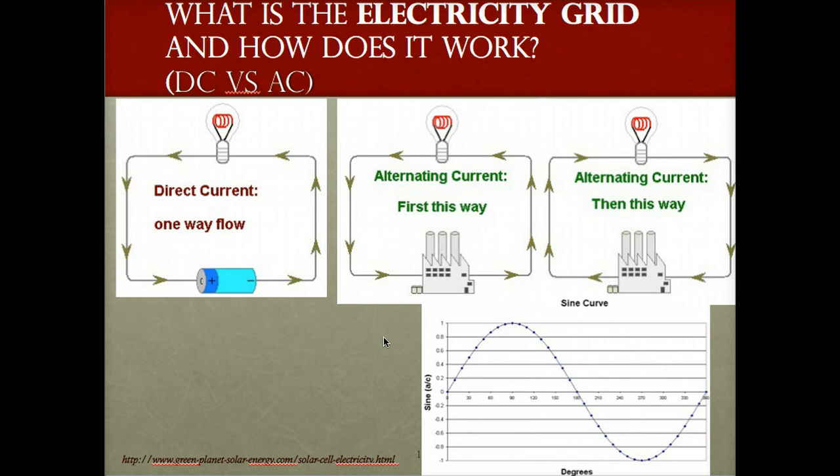One, you will be learning about the three main sections of the U.S. grid: East, West, and Texas. These sections are seen as completely different parts of the overall grid because they run on different frequencies. Although they all run on alternating current, their sine waves don't line up with each other. So if a generator in Texas wants to send electricity to Arizona, for example, that electricity has to go through a special and very expensive transformation process to be converted from Texas alternating current to Western alternating current.